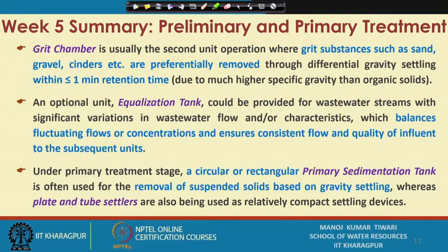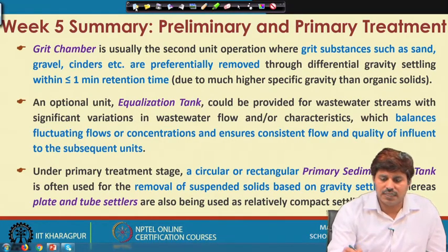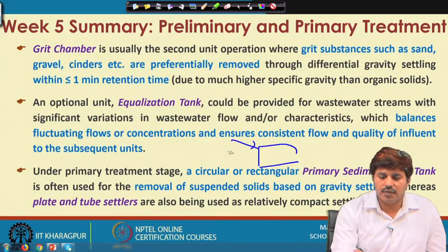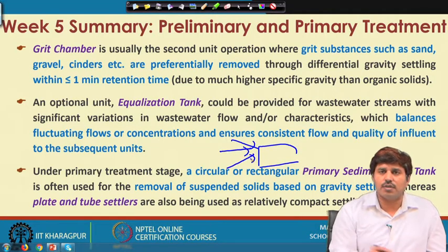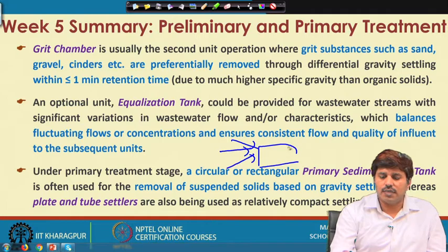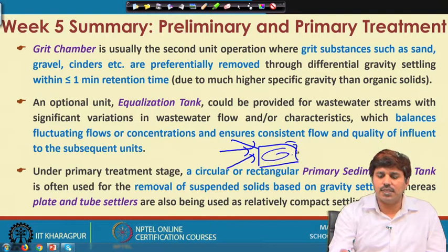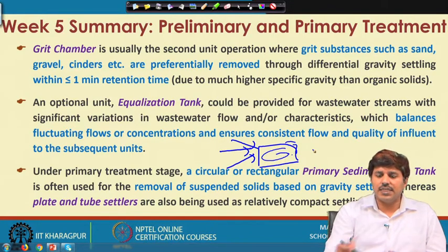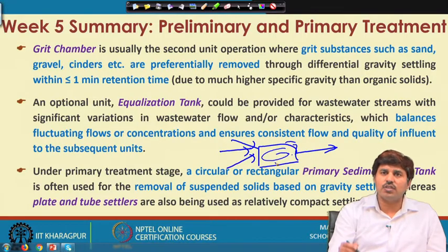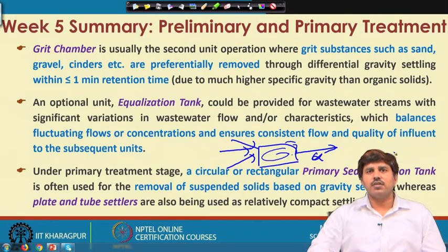It is a fairly simple tank where the wastewater inflow comes. We can actually have multiple channels. So, let us say this is a tank, and we have 2-3 different streams of wastewater coming in, and we will retain it for some time, 6 to 8 hours, sometimes even 12 hours. It is retained in here, then the waste gets homogenized, and from here it is pumped. The homogenized waste is pumped at a constant discharge for all subsequent units. So, depending on the need we can go for an equalization tank.